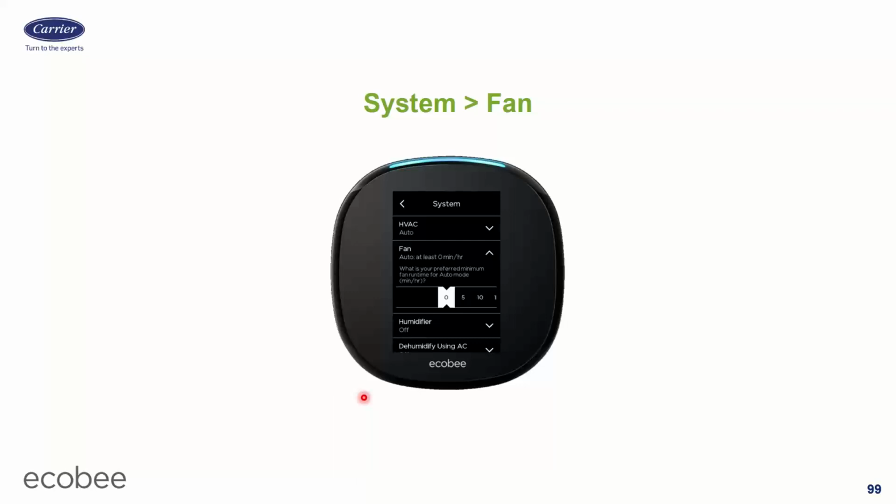So what I could do here is say, I want to run the fan 15 minutes out of the hour, no matter what. Well, if the fan's already on continuous anyway, then obviously it's already on, right? But if it's in the auto mode and it ran 30 minutes out of the hour, even though I only asked for 15 because I needed 30 minutes of heat, fine, I'm covered. But if it only ran 6 minutes of heat and I asked it on this screen right here for 15, it does the math and says, well, you asked for 15. I only gave you 6 with the W calls. So I owe you 9 minutes of fan.